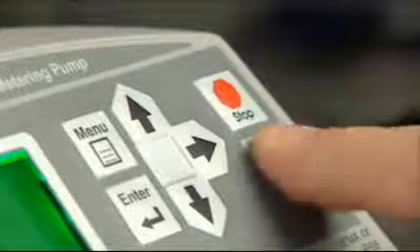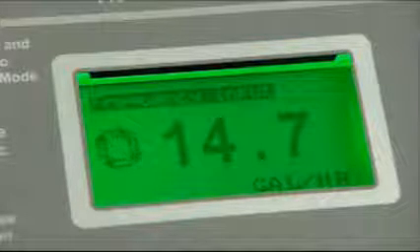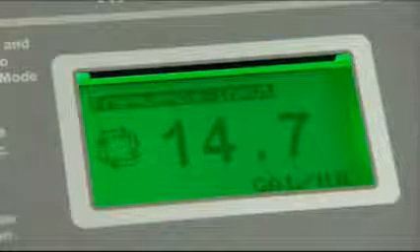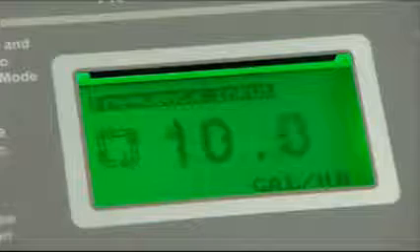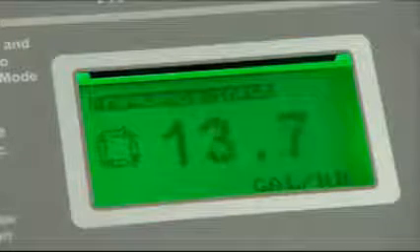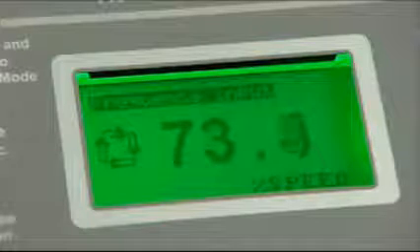Use the front panel Mode button to select the frequency input operating mode. Press the Start button. As the meter's output frequency changes, the pump's output will change as configured. To view the incoming frequency signal value, press the right arrow button.